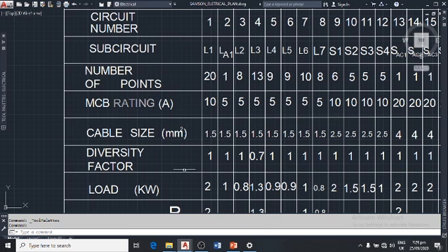So if you have 2000 watts, and you have 220 volts, then dividing that, we'll be having up to 10 ampere. You're having less than 10 ampere current. That is saying 2000 divided by 220. So you're having less than 10 ampere. Now, since you'll be having less than 10 ampere, it means that the circuit breaker that's up to 10 ampere will be used to control the L1 on the distribution board.